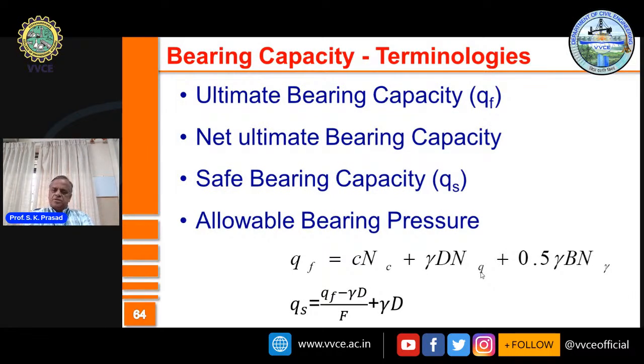I told you that bearing capacity is a very important parameter used in the design of foundations. I said that bearing capacity is a simple word, but it is preceded by some prefix. Ultimate bearing capacity is the maximum pressure soil can take at the foundation level. And any extra pressure you apply, soil will fail. We always express bearing capacity in the units of pressure, kilonewton per meter square, megapascal, and so on.